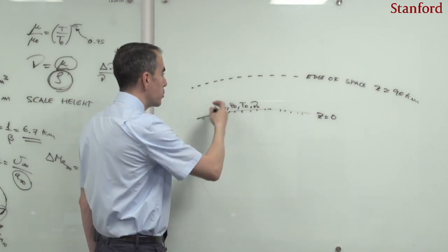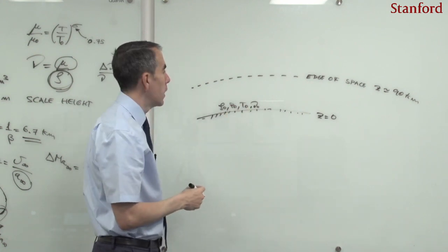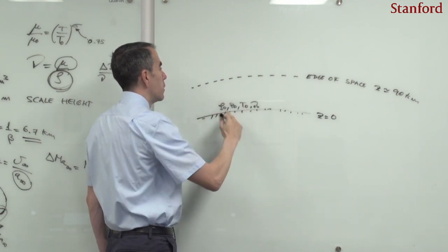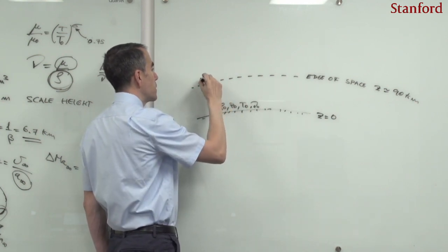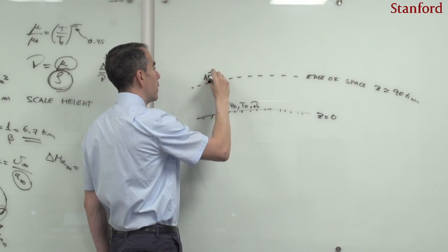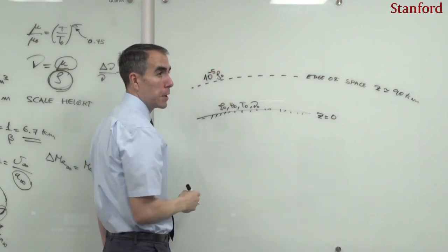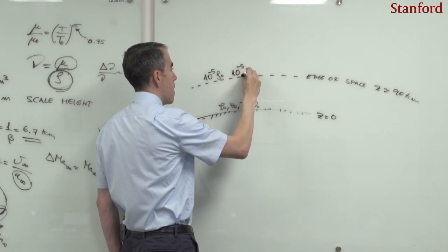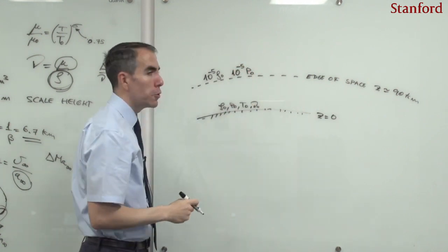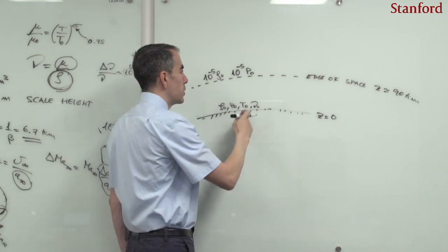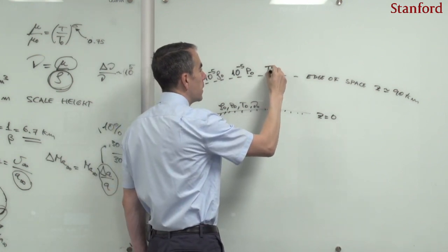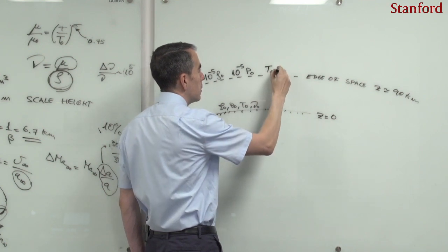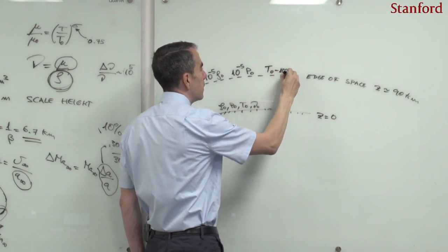From the conversation that we just had, we have learned that here at the edge of space, we go from these values to, for instance, a density which is 10 to the minus 5 times the density at sea level, to a pressure which is 10 to the minus 5 times the pressure at sea level, to a temperature that is going to vary, but not that much. So it's going to be just the sea level temperature and perhaps, let's say, minus 100 kelvins.